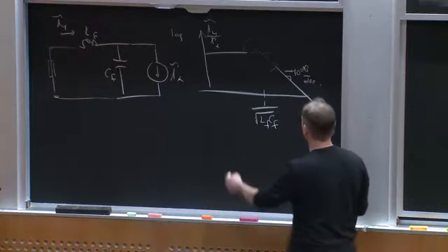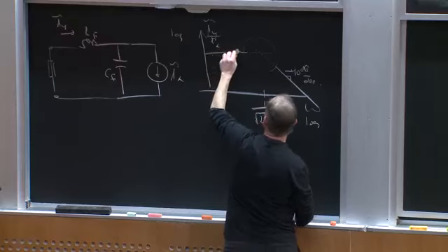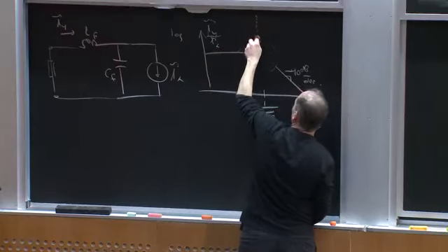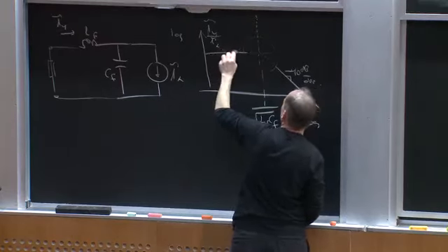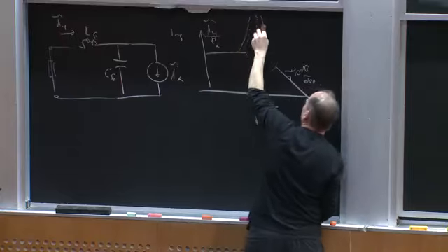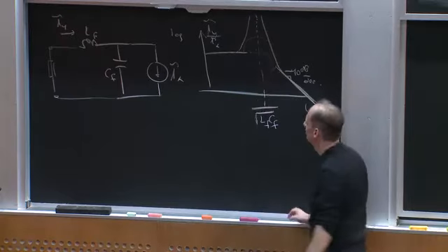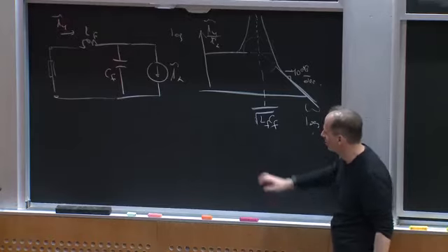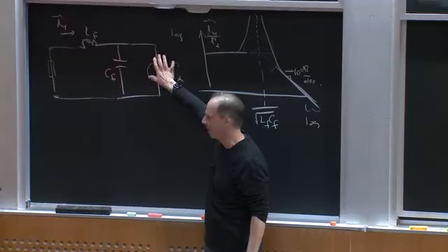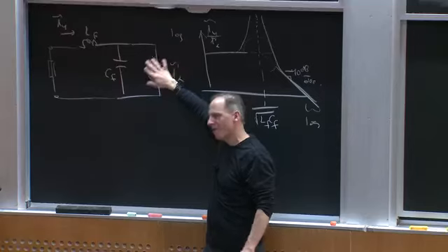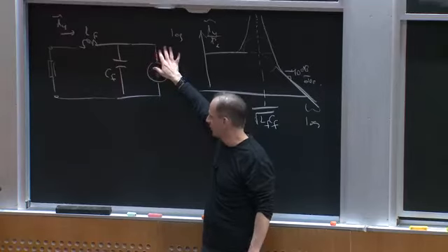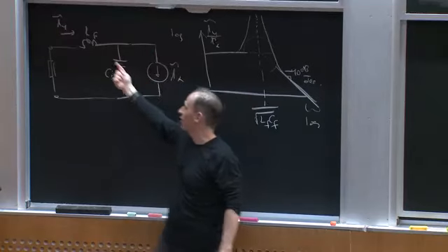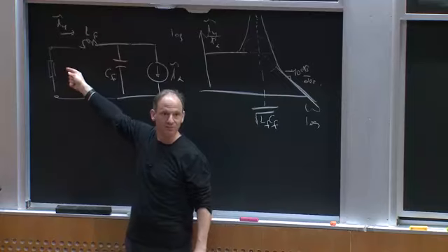So the current gain here actually does something like this. It goes off to infinity in this simplified case. It would do something like this, which is pretty bad. If you imagine that the converter somehow had some small amount that was drawing at some low frequency near this cutoff, it would drive this input filter nuts.